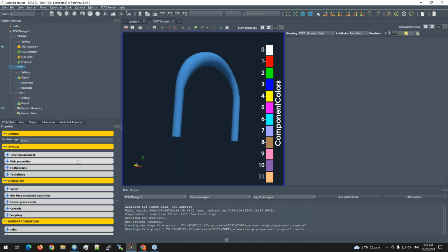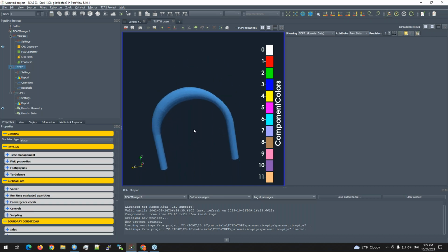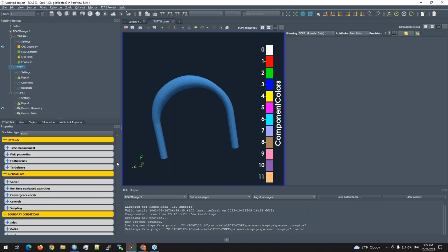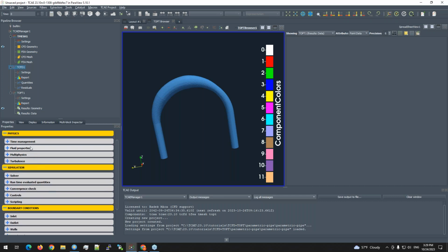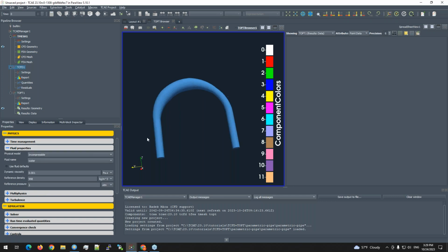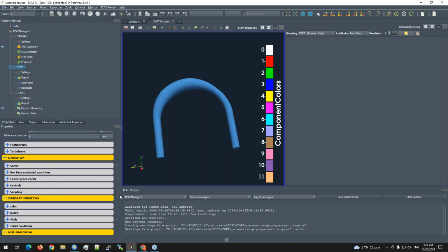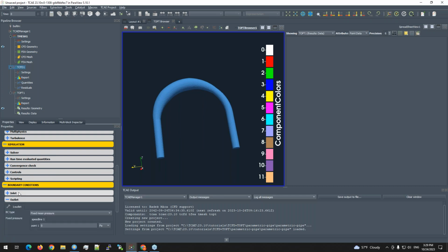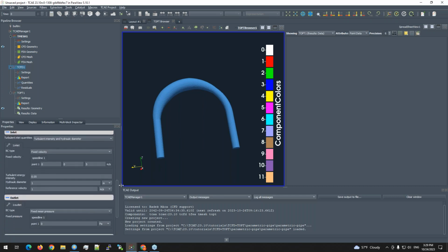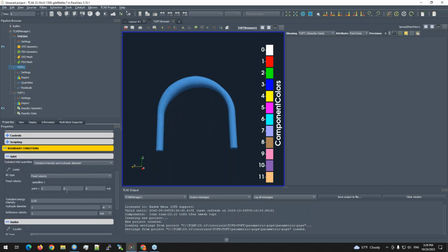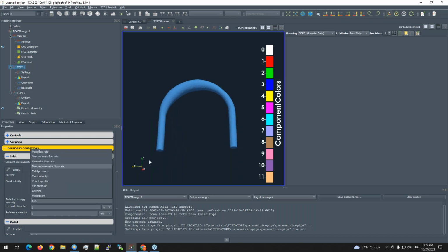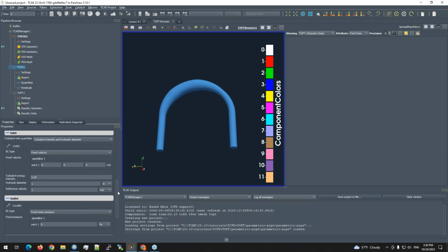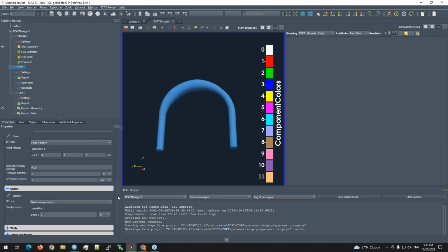So you will preset the CFD simulation in a standard way. You preset all necessary things like fluid properties. Here we have water, a piping system for the water, and you will set boundary conditions. Here we have 5 meters per second at the inlet, or you can set the flow rate for which you would like to optimize the shape, and run the simulation.